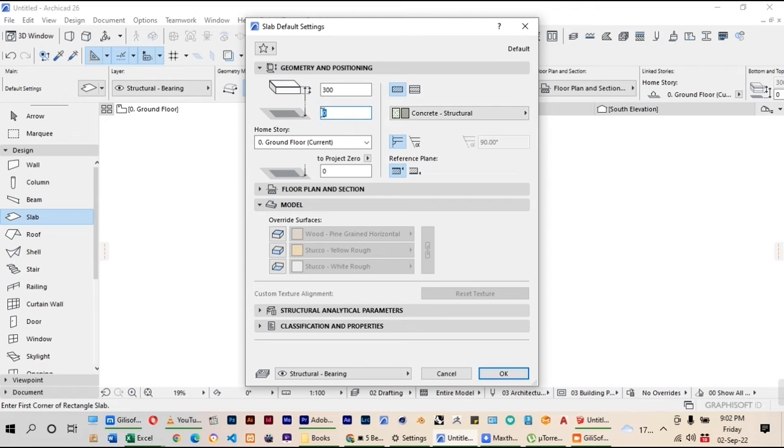What we normally do, the first measurement is the total height from the ground level 0 to the height of our object. If the coffee table is 450 millimeters, then we should put 450, and the top part defines the height of our worktop, which is, let's say, 30.